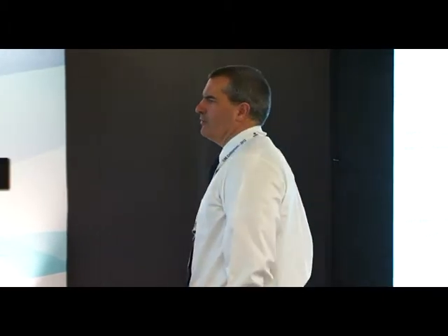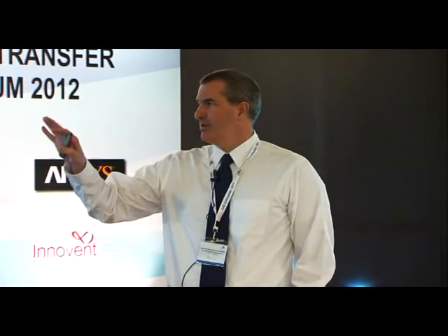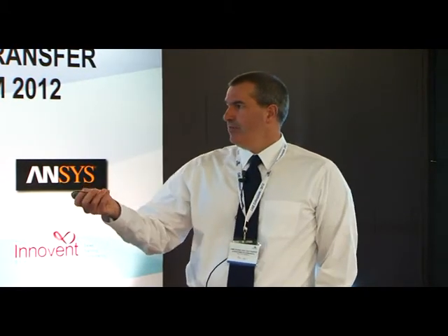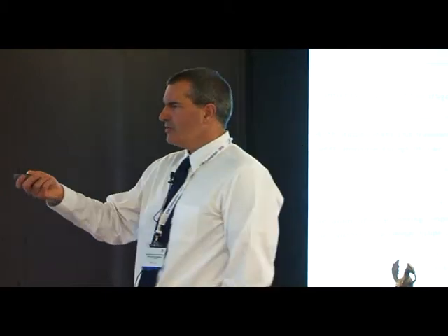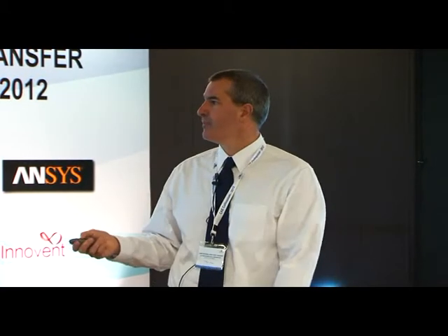So what did we set out to do? We wanted to take this completely cooled turbine stage model and run it two different ways. We wanted to run it the old way, which is a steady state analysis, and then we wanted to take that exact same model and turn it on transiently and start to capture the interaction between the vane and the blade. So that's the way we set the model up, because what we want to do is have exact back-to-back influence of what is the unsteadiness.